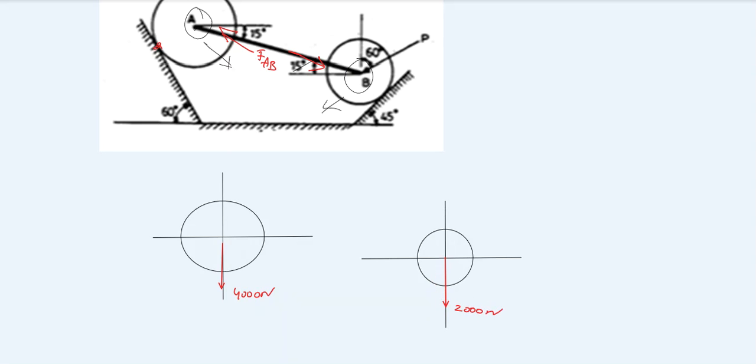We have a contact here. This is contact number 1, and we have a reaction R1 from this contact. This is 90 degrees with the plane. If you extend the horizontal plane, it is 30 degrees, because this is 60, this is 90, automatically 180 minus 90 minus 60, which is nothing but 30 degrees with the horizontal. So we have reaction R1 at 30 degrees to the horizontal.